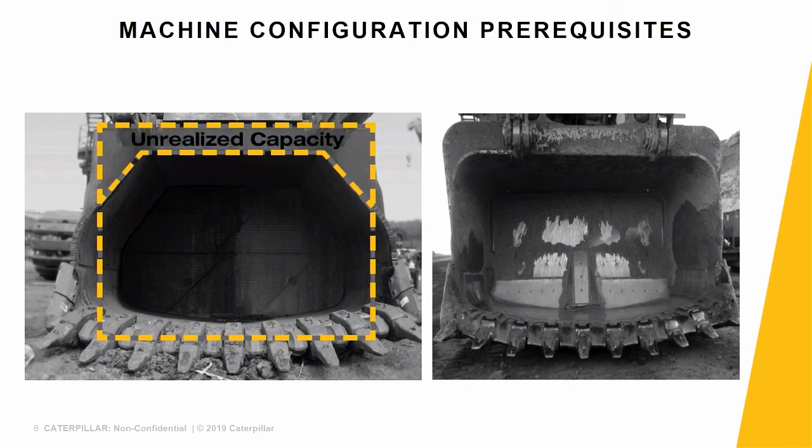Well, it depends on where you're going to start from. If you've got an older machine that's sized at one size, and now you want to upsize that, you're already experiencing life. So there's so many factors that go into that: machine fatigue, age, and where you're at in your rebuild cycle and component replacement. So that's kind of a hard question to answer. We know that on an older machine, if you suddenly start upsizing it, you're probably going to see some lower component life. So it may increase your maintenance costs.